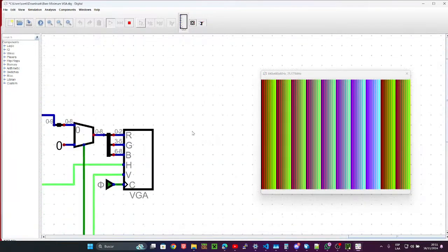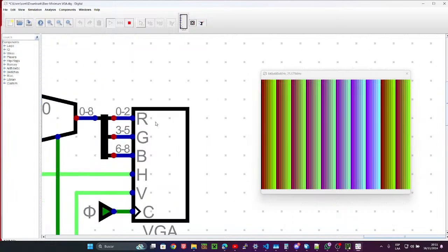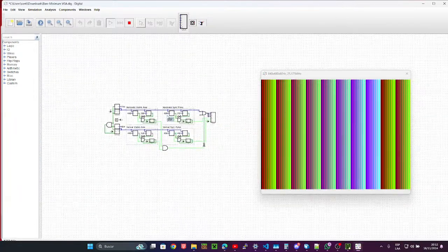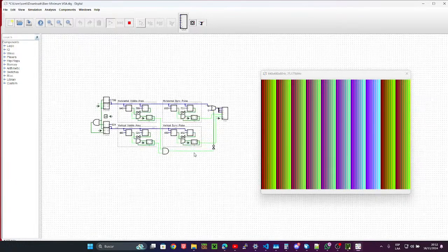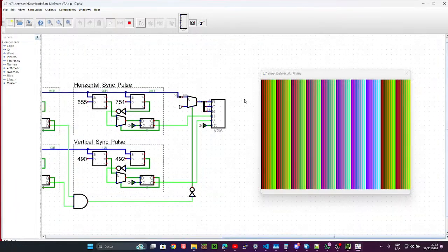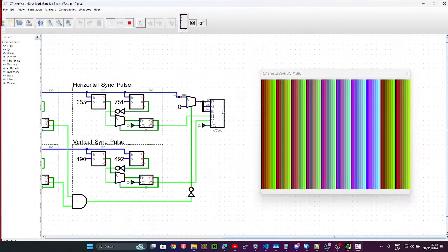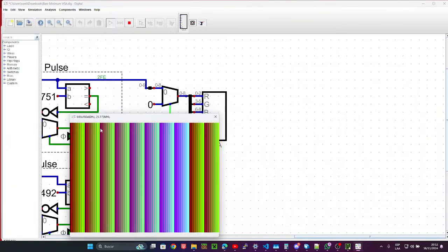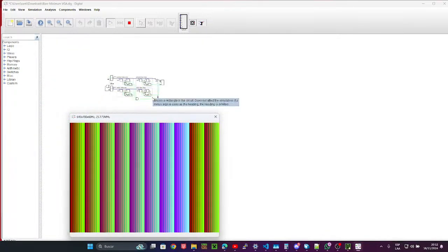Oh, you're right. You just need a different size bus. Also, it can take non-uniform sizes. So for 16-bit, you can do RGB 565. For 8-bit, you can do RGB 332. And I think it goes all the way up to RGB 888, but I'm not sure. There was a limit: if you give it a bus size too big, it's just not going to do anything with it.